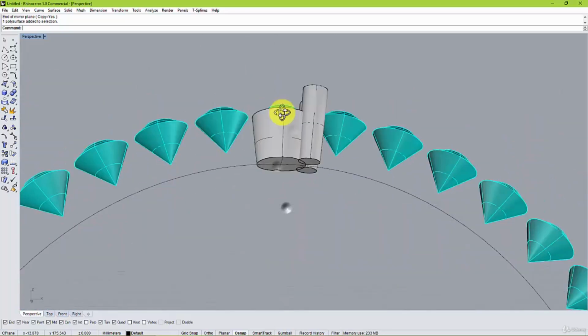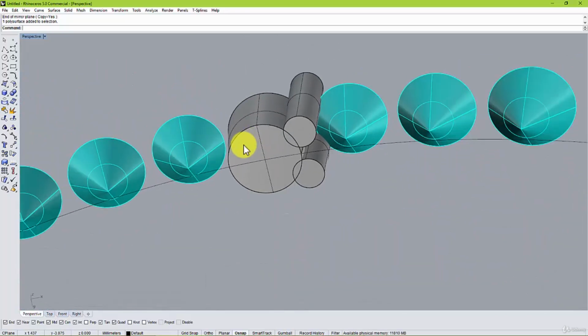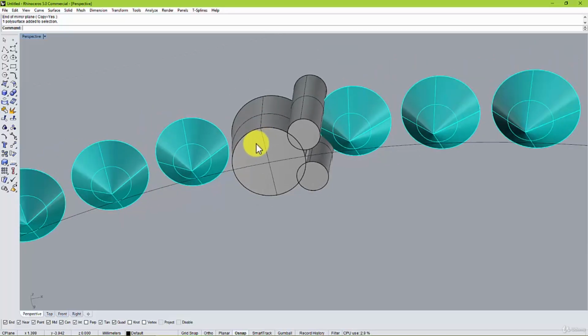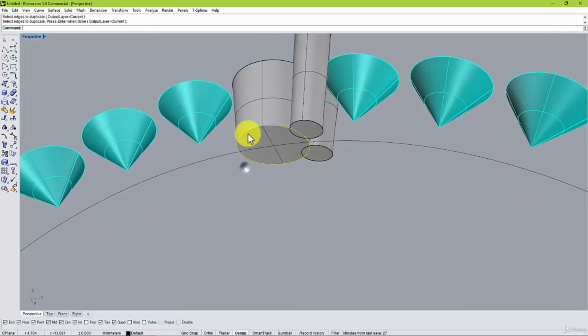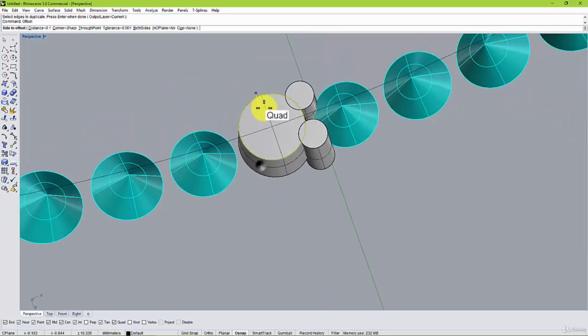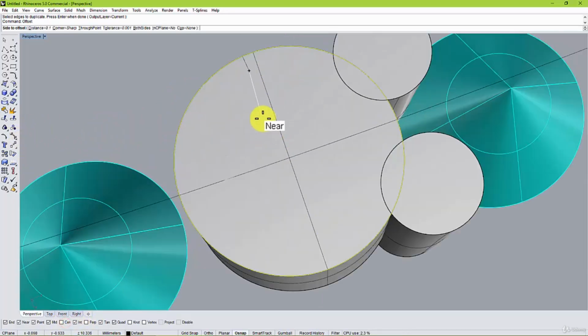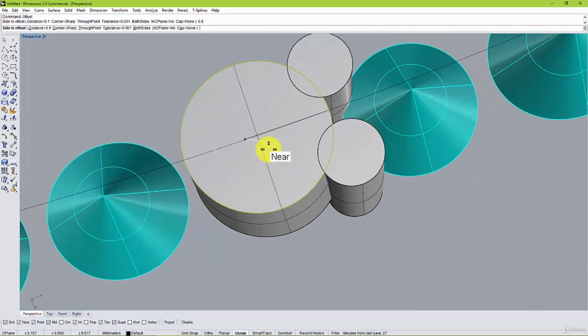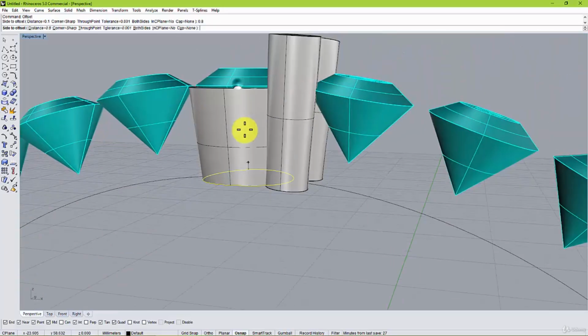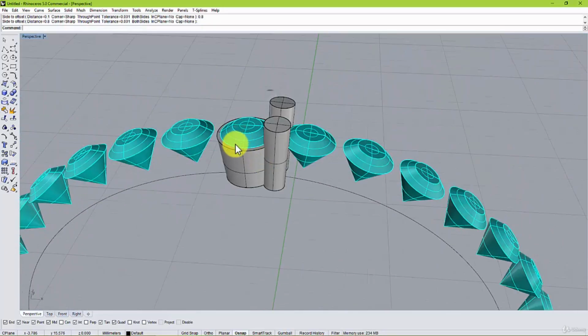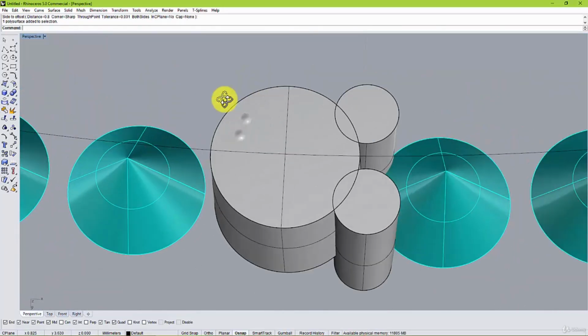Okay. Let's see if we can probably make a hole there. The main thing you need to consider is this wall thickness. So I duplicate edge, and I'm gonna make an offset. As you know, we probably need at least 0.8 thickness. You see 0.8 thickness goes there already, so in this case I would not do it. Okay, it's just that we don't have much metal.